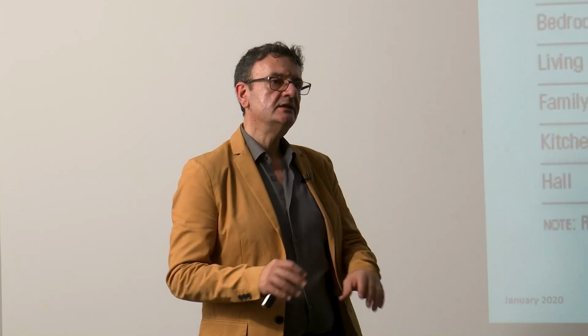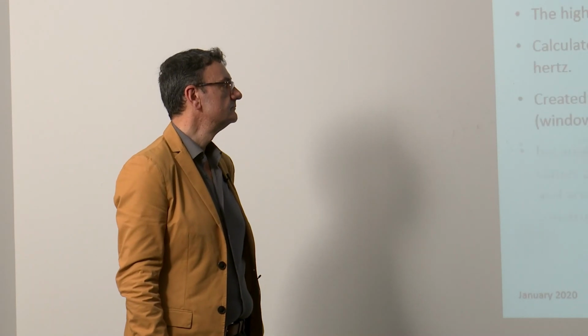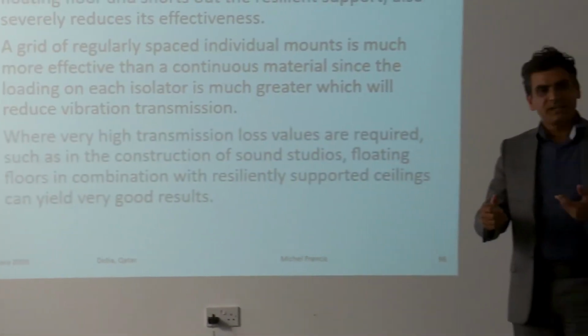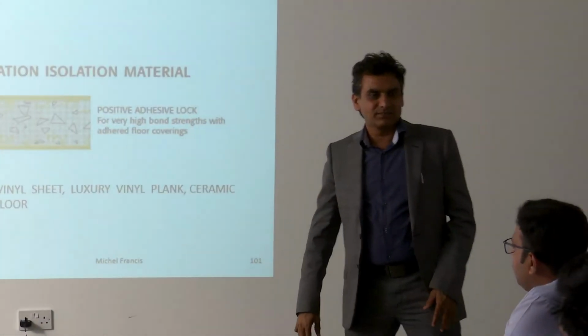So machine room. Machine room also, you would have the requirement of engineering. You will have the rating of the noise coming from that machine, how many dBs. You will have the requirement for the vibration isolators and the underlayment. All these requirements are going to be given to you by your engineer. This is just general. As a specific, we can get. Exactly. For the machine load, you will ask for the equipment, what is the load, what is the capacity, you get it. And with every equipment, it is already specified. So are they going to provide it?